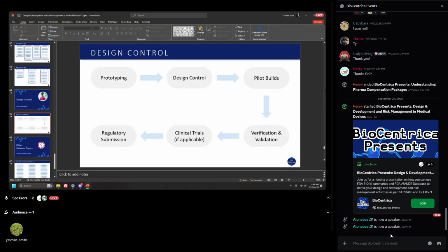That will be a new revision for that part. You have to update the assembly procedures, you have to update the inspection procedures, you have to update the drawings, you have to include the data sheets that are relevant to that component as well. So just to make sure that your purchasing team doesn't mess up and that you are getting the right part when it's received by the production team.